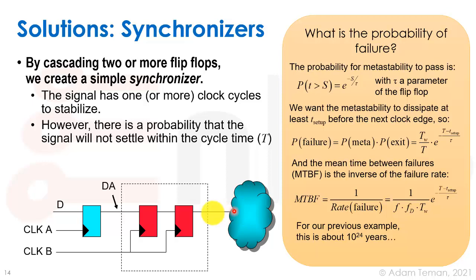Metastability is a huge problem. So we never want a metastable state to be on this net at any time. So what do we do, and why does a synchronizer solve that? Because we can get a metastable state on this net over here. We will get it every once in a while. I don't know how long it'll be. There are all kinds of calculations for when you'll get metastability, but we'll get a metastable state, something in the middle.